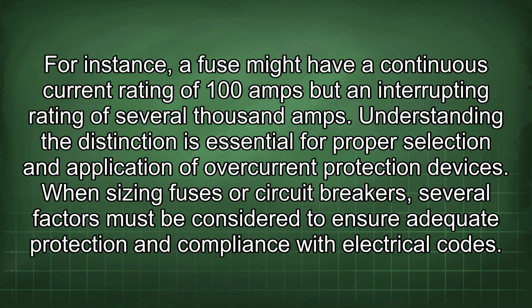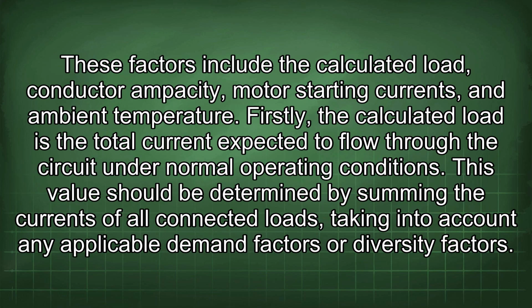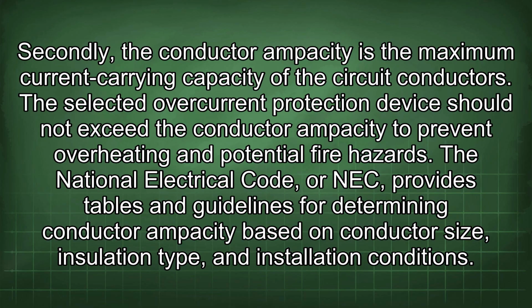When sizing fuses or circuit breakers, several factors must be considered to ensure adequate protection and compliance with electrical codes. These factors include the calculated load, conductor ampacity, motor starting currents, and ambient temperature. Firstly, the calculated load is the total current expected to flow through the circuit under normal operating conditions. This value should be determined by summing the currents of all connected loads, taking into account any applicable demand factors or diversity factors. Secondly, the conductor ampacity is the maximum current carrying capacity of the circuit conductors.